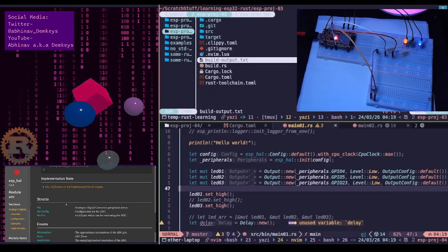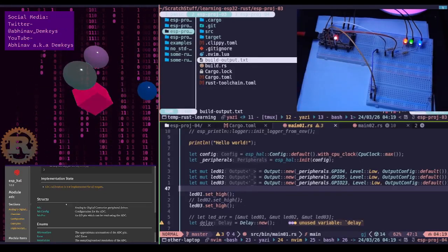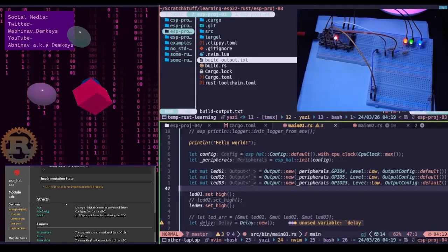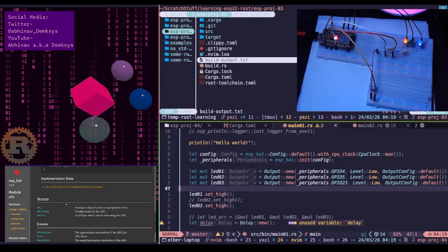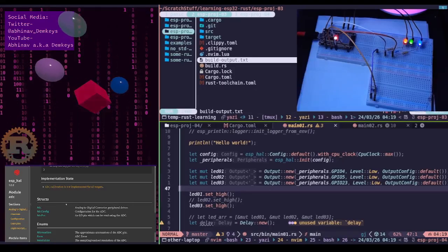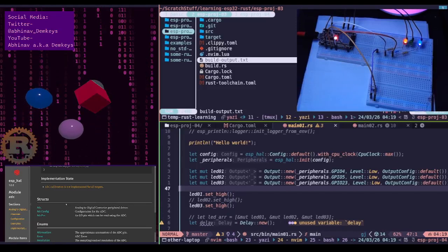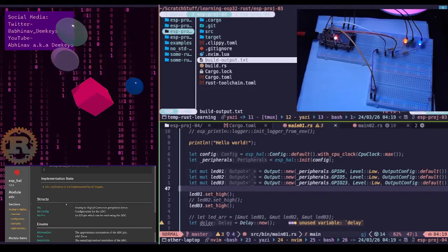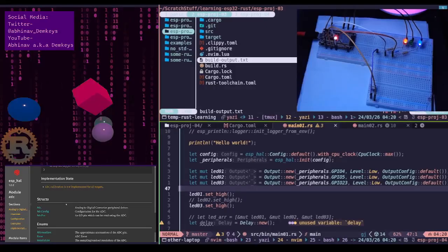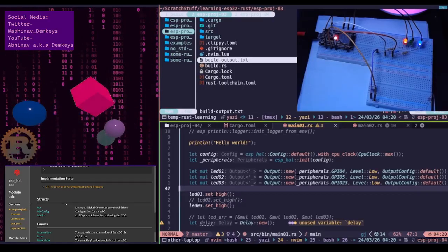Relative changes still work. If you turn a potentiometer, the numbers will go up. If you put a light sensor in a dark room, the numbers will go down. Okay, good to know. For learning how to use a peripheral, this is 100% sufficient. Then the frustrating part, which is the lying multimeter. If you use a multimeter to check the battery and it says 3.3 volts, but your ESP32 says 2.9 volts, you might spend an hour debugging your code thinking you have a bug. The bug is just the uncalibrated hardware.